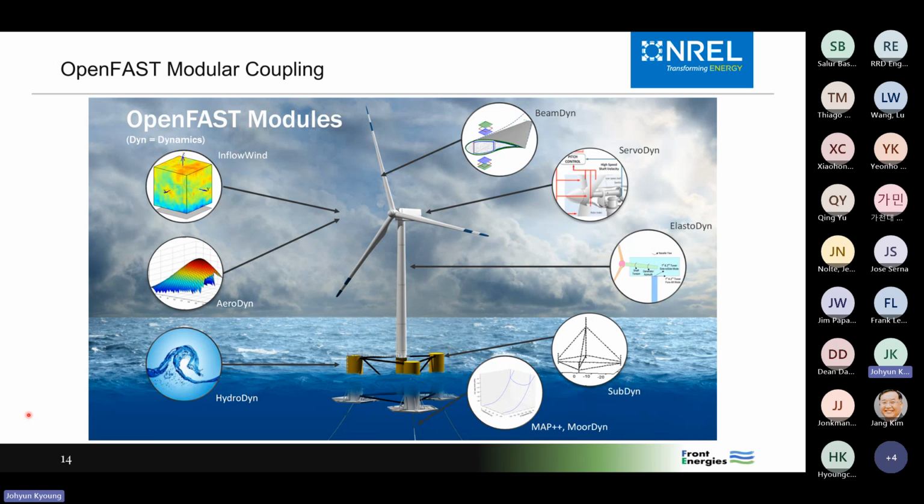Different mooring modules. MoorDyn is our closest one to OrcaFlex, basically a lumped mass formulation connected by springs. ServoDyn is our main controller. There are some built-in options, but mostly it's an interface either to controller dynamic link libraries or things like Simulink interfaces.